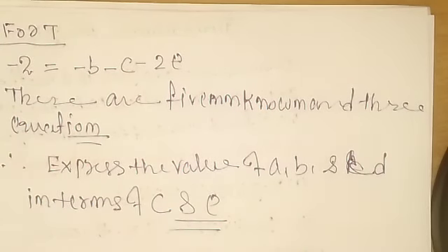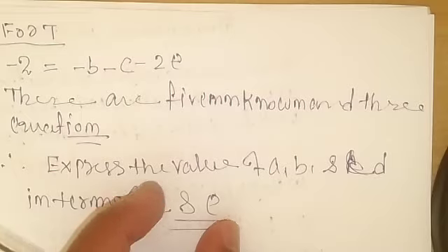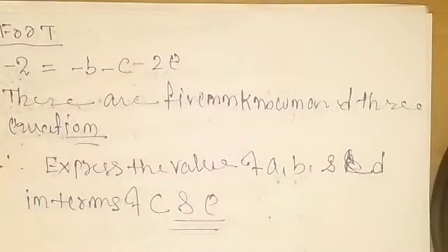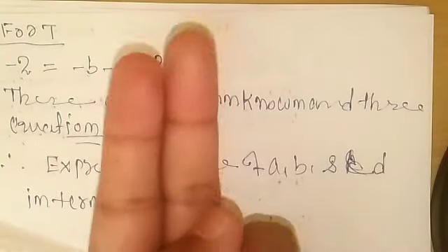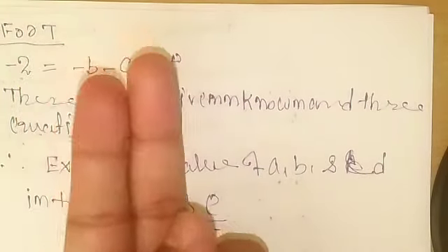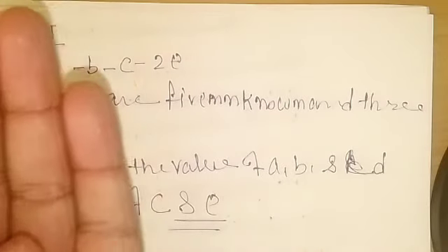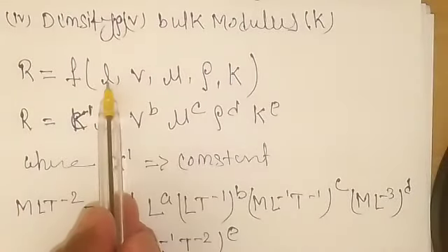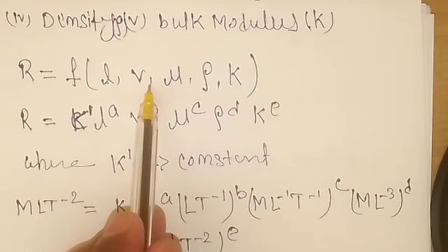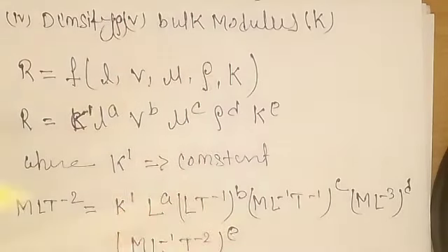At that time you will get the idea why we have not chosen the others. As I told you, the priority goes first to geometric properties, meaning length, distance, height, and so on. Then velocity, acceleration, and so on. Then flow properties like density and viscosity. So L comes under the geometric properties, V under the velocities, and rho under the flow properties.